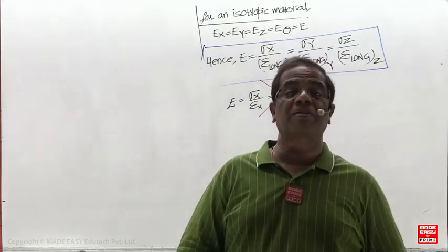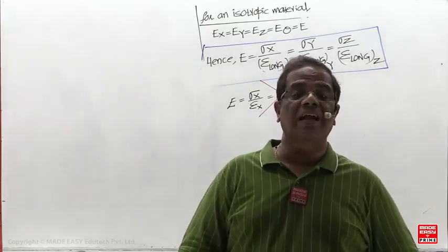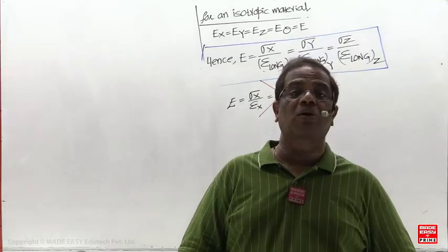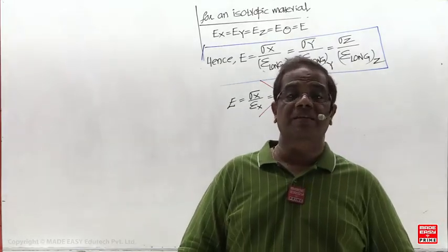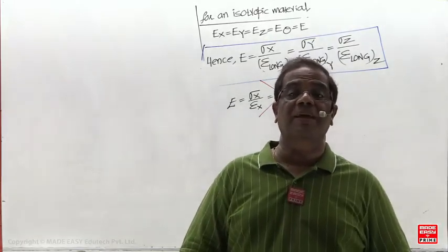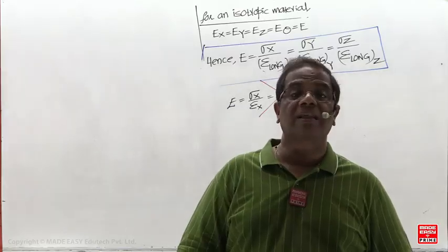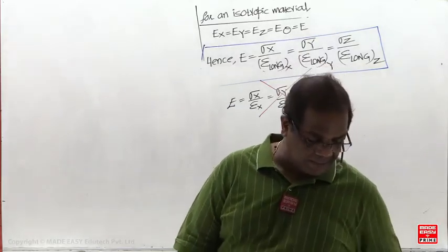Superposition means we assume each load is acting alone. First I assume Px acting alone, then Py acting alone, then Pz acting alone. When Px, Py, Pz act alone, each is a uniaxial state of stress.